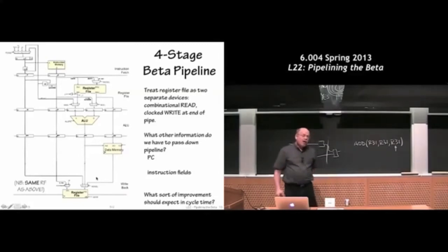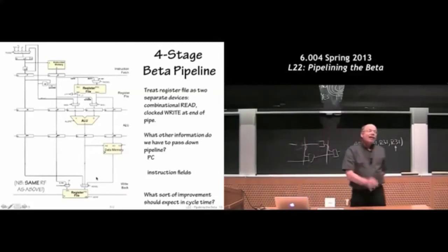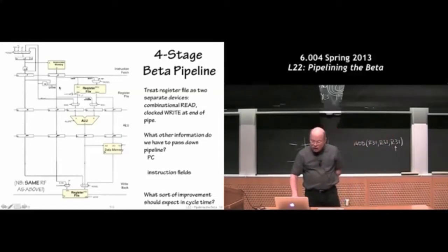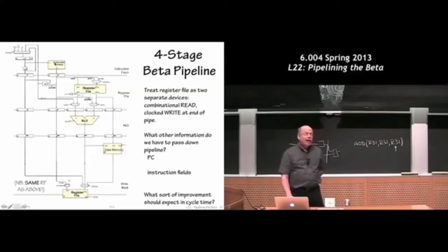Okay, so deep breath. We added that one pipeline stage up here, and then we had to deal with this backwards wire. Right, this idea that we're making a branch decision here and doing some computation that affected what we wanted to do in the earlier pipeline stage, and that caused us to add some hardware and do some annulment and deal with that. Okay, let's go ahead and continue our exploration about adding additional pipeline stages.